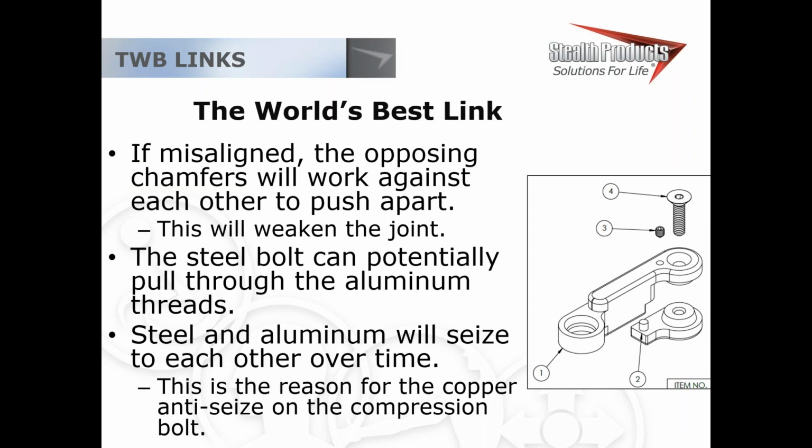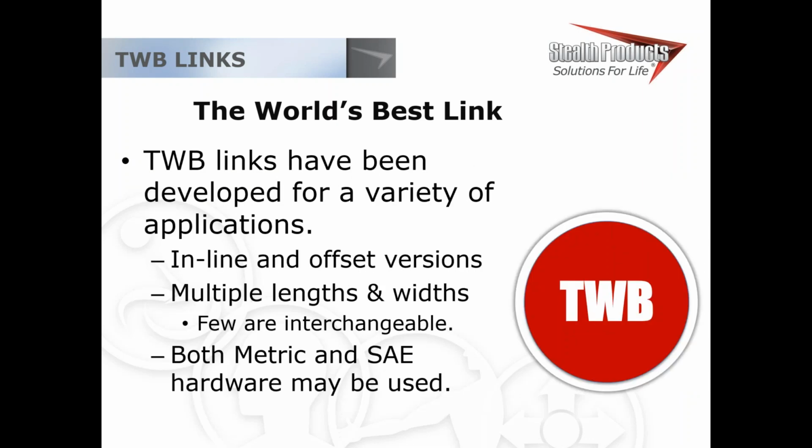It only has a 2 to 3 cycle rating. So in theory, when they were going to set it for their final position, if you're going by the copper anti-seize manufacturer recommendation, they should be putting more anti-seize on at that point. So it's a lot of minor things that all added up to some crazy stuff going on with that bolt.